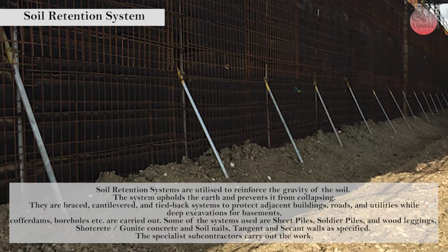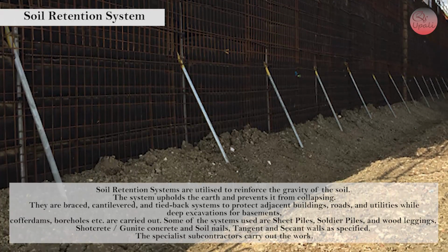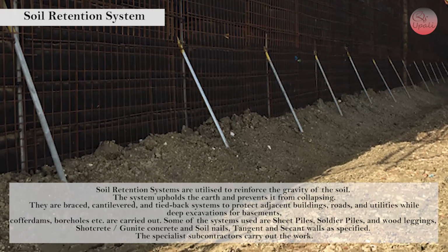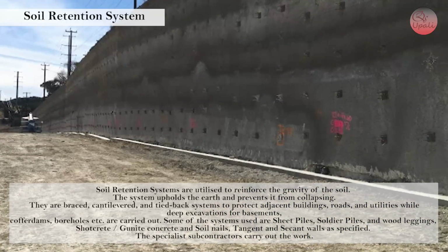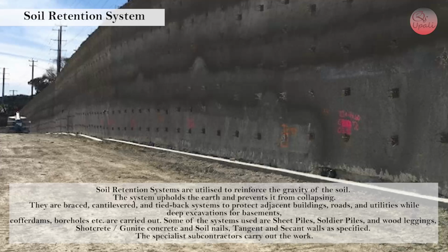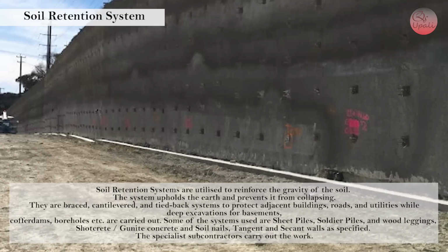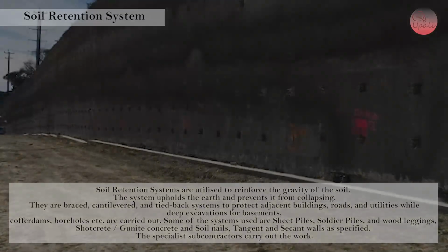Some of the systems used are sheet piles, soldier piles and wood lagging, shotcrete, gunite, concrete and soil nails, tangent and secant walls as specified. The specialist subcontractors carry out the work.